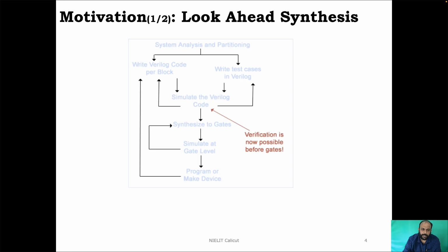Now, if you look at the motivation, this is one important aspect that Verilog, or any hardware description language for that matter, supports, which is not really supported by other design entry mechanisms like schematics. We can call it look ahead synthesis, because if the design is entered using a hardware description language, one obvious advantage is that it can be used to thoroughly debug the design before we go to the more time consuming processes involved in the synthesis. I already explained, synthesis here means converting our